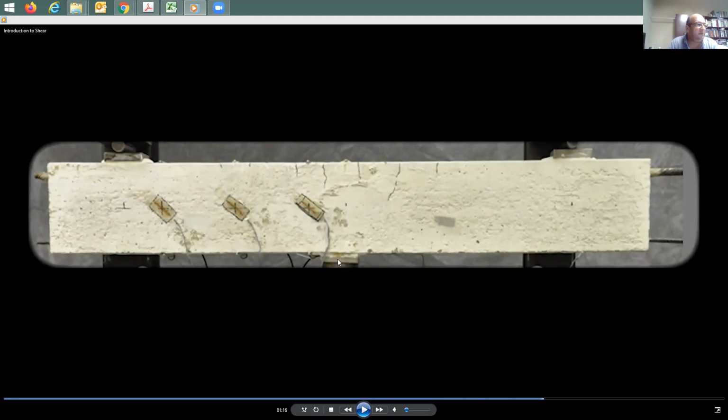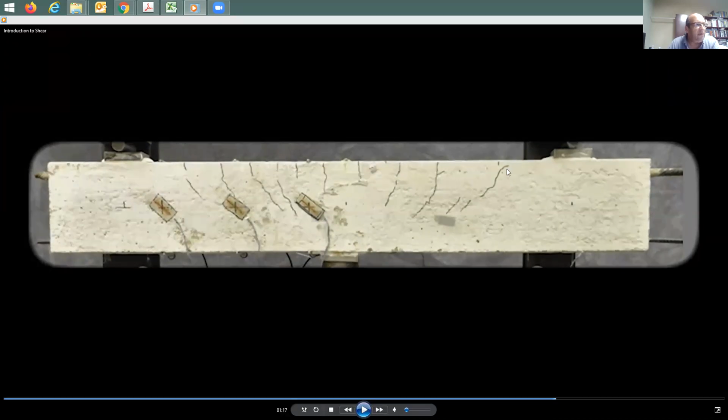Look, when they start to put some loading on, you start to have some cracks here. And they put some strain gauges here. The strain gauges, and you see the wires coming out of them, tell you the strain in the face of the concrete beam. Now, at the beginning, you're going to have some flexure cracks. The beam is going to start to crack. And look what happened. This is a flexure crack to here only, to here only.